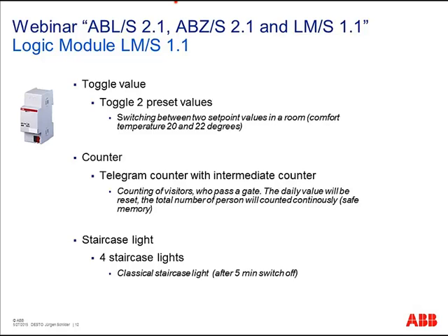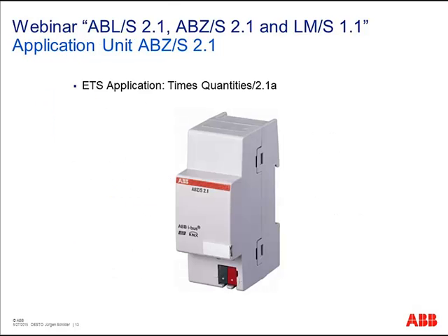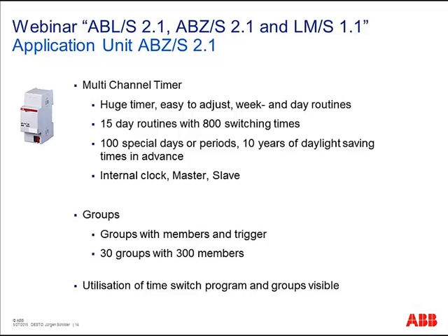Okay, let's go to the next component, the ABZS 2.1. The application module with time functions and group functions. So before I go into the ETS, I have a kind of summary of the functions itself, what is behind this component. First of all, there is a huge timer inside, a multi-channel timer, where you can adjust day routines, week routines. I will show how it works inside the ETS.